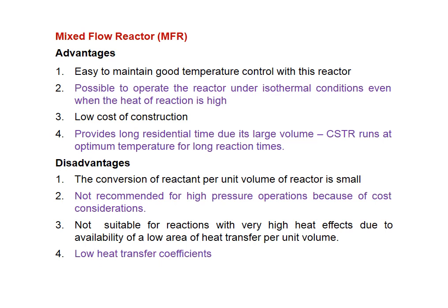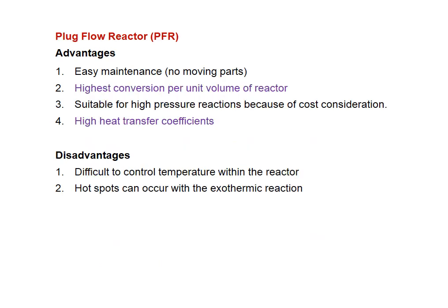CSTR runs at optimal temperature for long reaction times. Whereas the disadvantages: the conversion of reactant per unit volume of reactor is small, it is not recommended for high pressure operations because of cost consideration, and it is not suitable for reactions with very high heat effects due to the low area of heat transfer per volume and low heat transfer coefficient.